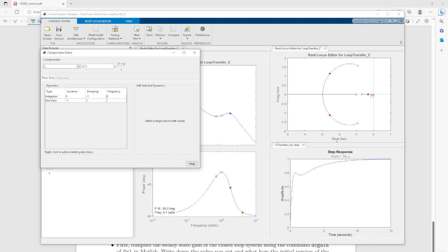Matlab already updated our curve here, and we see this root locus curve now looks the following. This goes to the left. We have integral action, and here we are actually back to a similar behavior as before, without that integrator. So this is here the integrator zero part, which stabilizes our integrator, and this zero now takes, as before, care of our two poles to increase the stability. So the question is now where you place the poles, what gain do you choose?